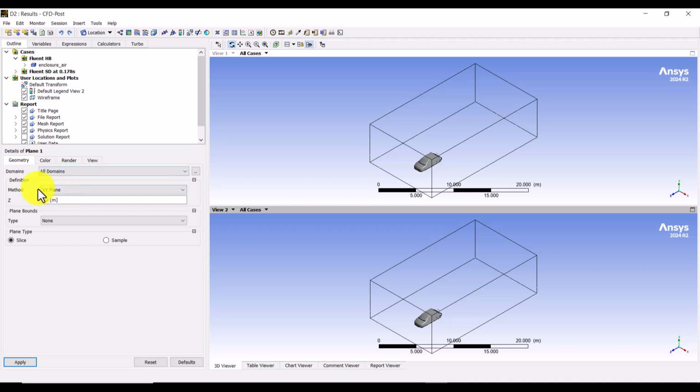And now I've got access to the domain extents. For this plane, regarding this origin, it would be in the ZY direction. So I'm going to change the method to ZY, or YZ in the first place. I think regarding the reference origin and the initial setup as in SpaceClaim, the X value of 0 would be put just in the middle.